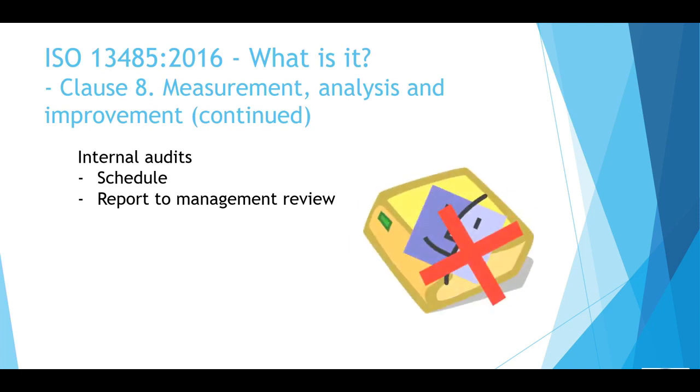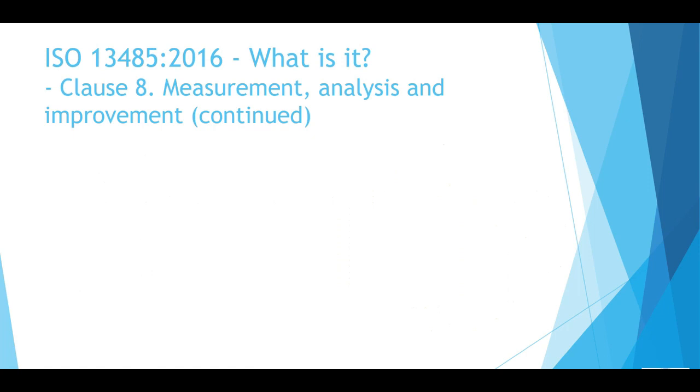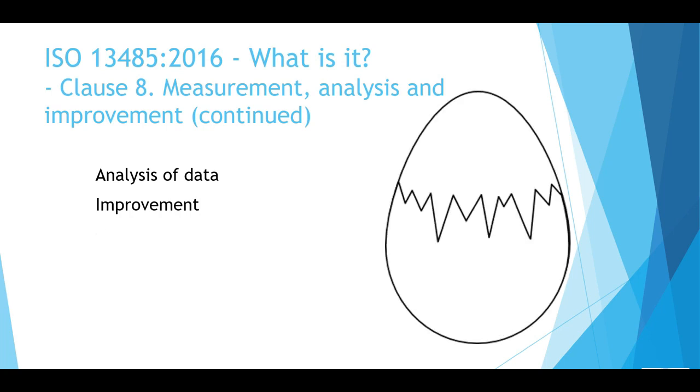You have to monitor and measure product during the manufacturing process to identify non-conforming product and take appropriate action to isolate such product and prevent unintended delivery or use. Finally, you are required to analyze data about your organization's QMS in order to evaluate its suitability and effectiveness and improve where indicated. Where appropriate, you need to take corrective and preventive action in order to maintain QMS suitability, adequacy and effectiveness, and ensure medical device safety and performance.